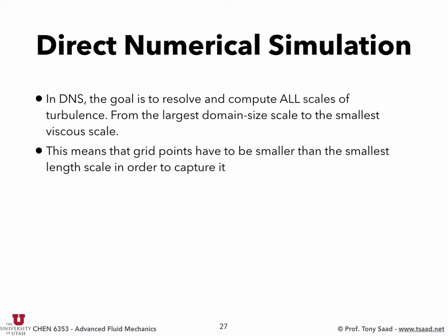And the same thing applies when we're doing fluid flow. Typically in a fluid flow calculation we have what we call cells, where each cell contains one value for the velocity, okay? And let's say you have an eddy. If you have an eddy that's this big, well, you can capture it because you have velocity here, velocity there, velocity here, and velocity here. You can have an idea of what the eddy looks like. But what if your eddy is this small?